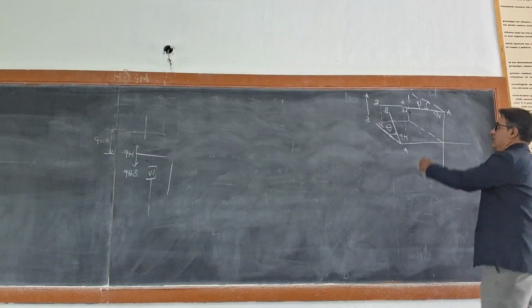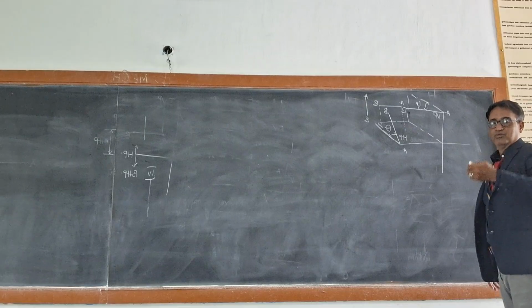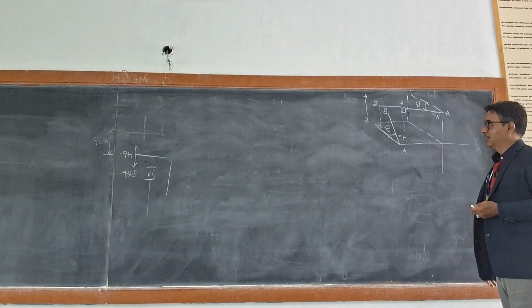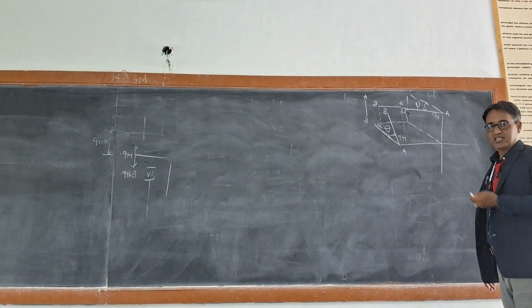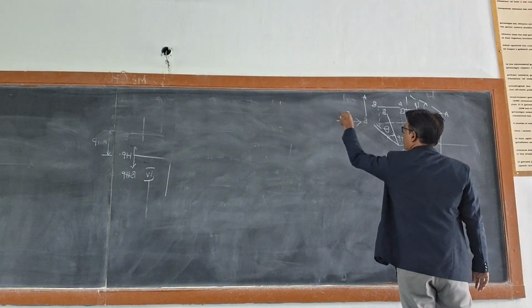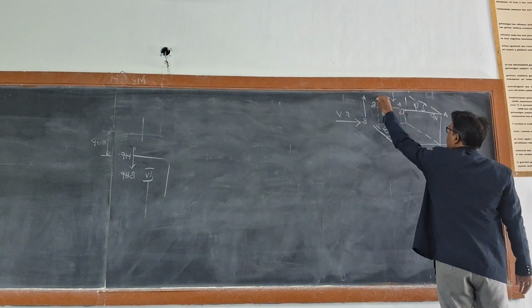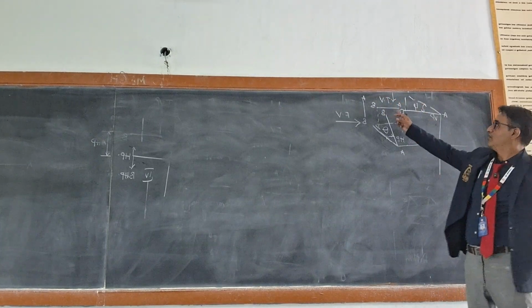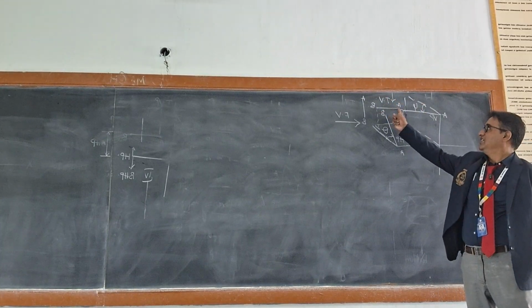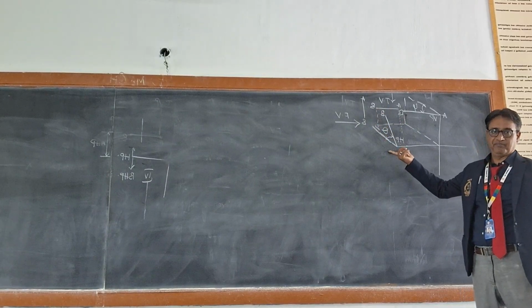And you are going to look at this object from different views. As I have already discussed, there are about 6 different views, but here you are going to deal with only 2, which are the front view and the top view. When you look at the object from the top, the exact length will be projected onto the horizontal plane.